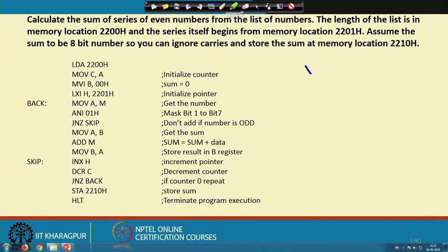So, if you consult the 8085 manual, then you can find out the individual number of bytes needed for individual instructions to compute the size of the program, and you can also find out the total number of clock cycles needed by individual instructions. So, you can trace through the program and compute the exact time needed for executing this program using 8085. That is why we can take help of assembly language programming.